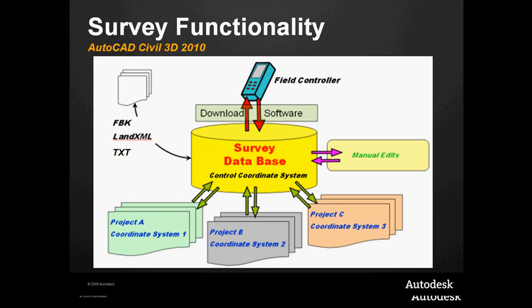It's flexible enough that we can generate line work straight from an ASCII file. I mean, we can generate line work straight from points off the screen. We can window the points and say read the codes, generate the line work, and it'll go from there. So that significantly increases our flexibility in the field, in that when I collect data now, it's the description that's the most important thing. I don't need special notes or anything like that added to the collection that will make my line work. I just have to add a description on the point and I'm done.